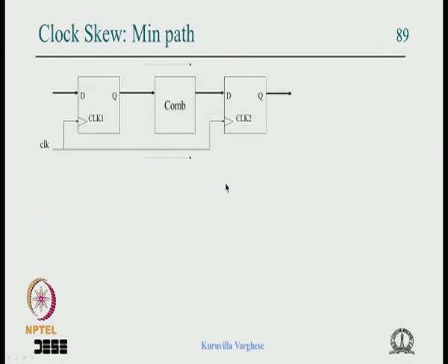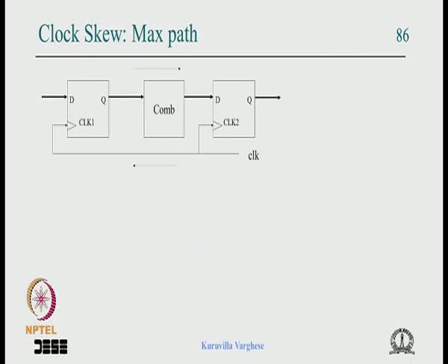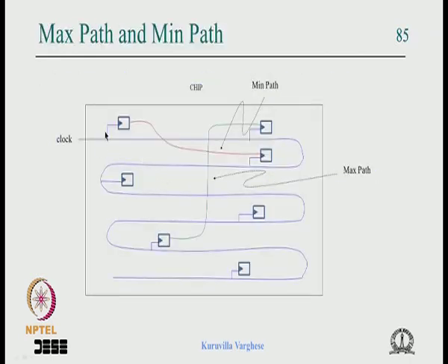So with respect to the earlier picture, we cannot route like this. As the clock tree goes, everything gets delayed because of the loading, and from this end to that end the delay is very high. So we cannot have such an arbitrary scheme of clock routing. The ideal thing would be that from the clock pad to any endpoint there should be an equal length of wire and an equal number of buffers.